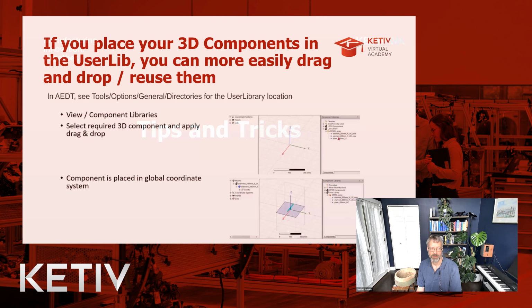And that's it. I just wanted to mention a few other tricks here. If you place your 3D components in the user library, then by right-clicking on View Component Libraries, you'll have access to those 3D components as a right-click, and you can just drag and drop them and reuse them in your design. So if you have a 3D component that you're planning to use in lots of different designs, sticking it in the user library is a great way to access it, use it, make it more friendly.